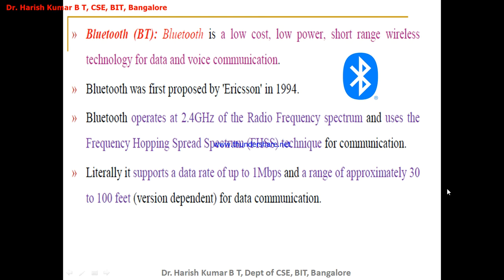Now Bluetooth is once again a low cost, low power and short range wireless communication technology. It was first proposed by Ericsson in the year 1994. It operates at 2.4 gigahertz, and the data rate is 1 Mbps, with a range of approximately 30 to 100 feet. These are all the specifications which you have to remember.